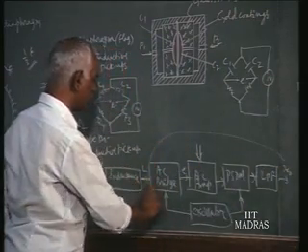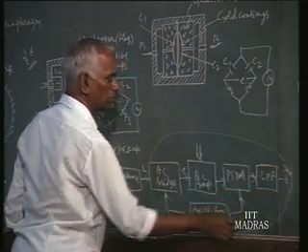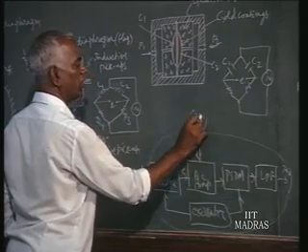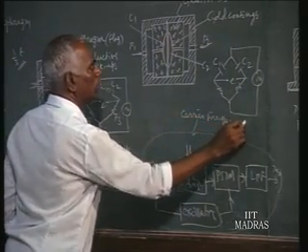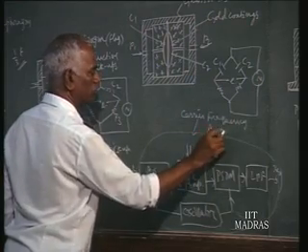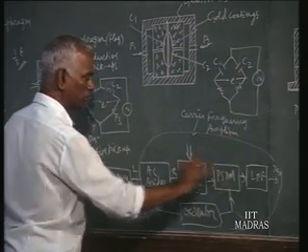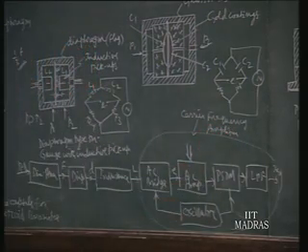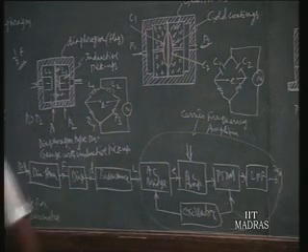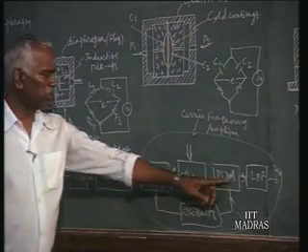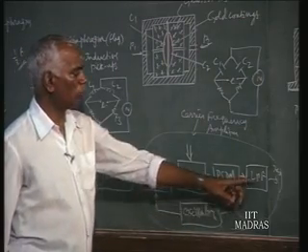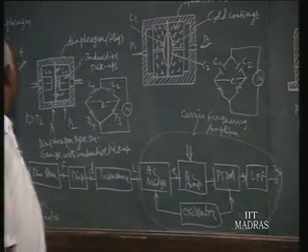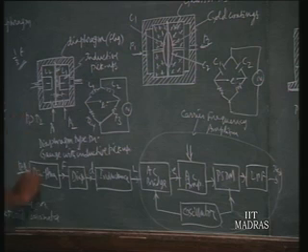This is your carrier frequency amplifier. This whole thing forms part of the carrier frequency amplifier, which you don't see like this, but this is what is in the detail which you have learnt earlier. So we get the output signal. That is the phase sensitive demodulator, the crystal oscillator from where we get the excitation, and the low pass filter, and we get the output signal. So that is how the inductance can be made use of to sense the deformation of the diaphragm into an electrical signal.